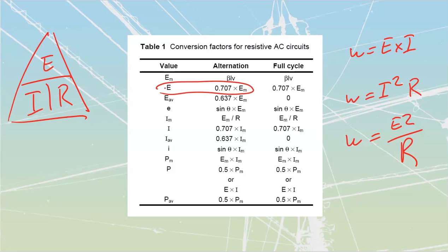That RMS value of voltage, we are then going to put into here along with the heat that we have, the 1500 watts, and then we're just going to cross multiply the R and the W, isolate, get the R up top, bring the W down below, which is then going to allow us to figure out the amount of resistance that we're going to have.